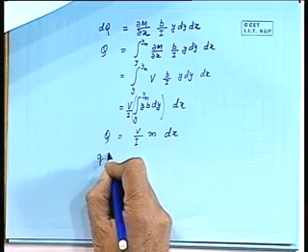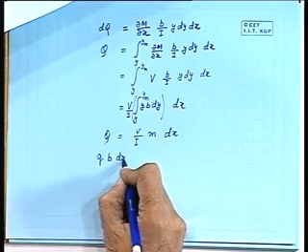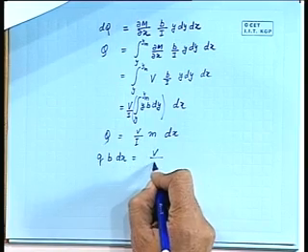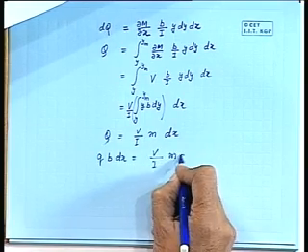So, at this interface, the cross sectional area is b into dx. B is the width, this is b, and this is dx. So, this is this area b into dx, and if the stress intensity there is this stress, so it is a horizontal shear. So, if I say that q is the stress, small q, then q into b into dx is equal to V by I m into dx.